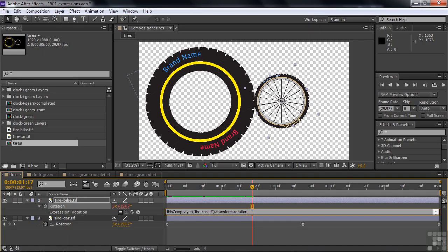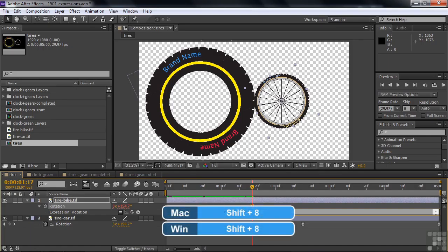And I want it to go in the other direction than the direction it's going now. I want it to go the opposite direction. So to do that, all I need to do is multiply times -1. It'll then impart a negative rotation instead of a positive rotation. To multiply, you just put an asterisk, Shift 8, and now -1.